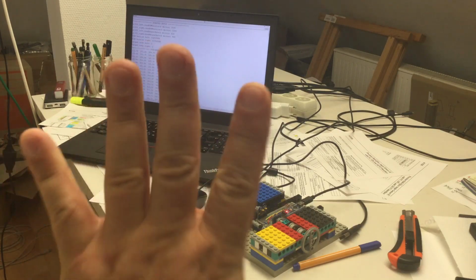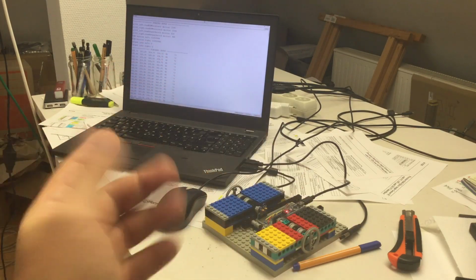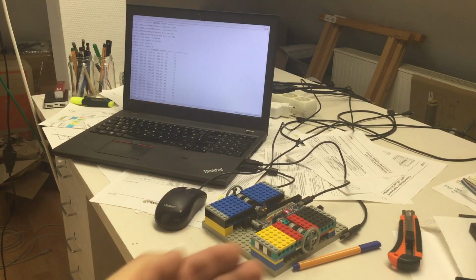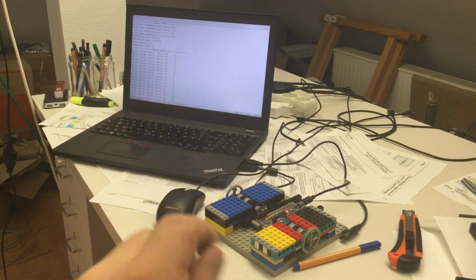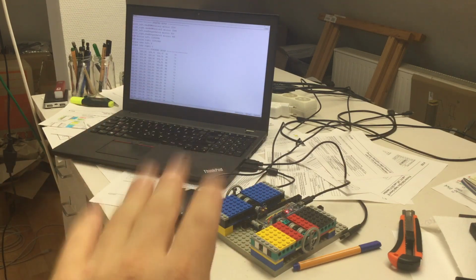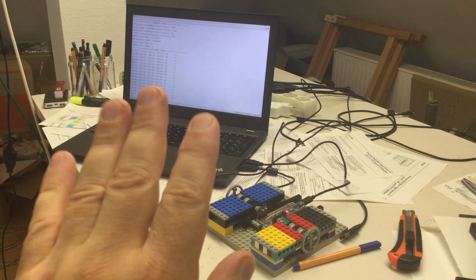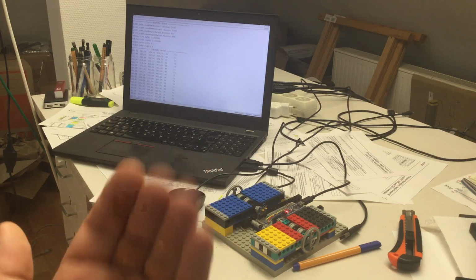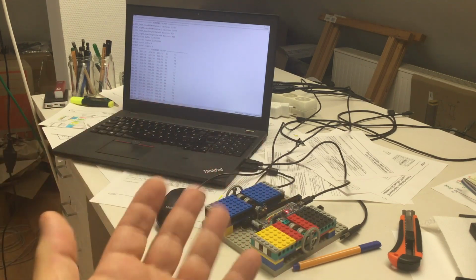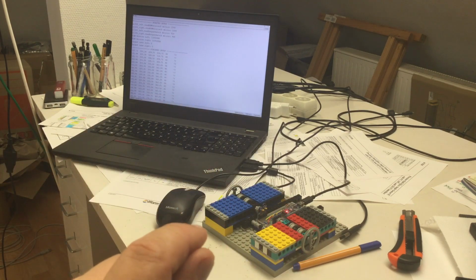Welcome back to the fourth part in the video series about the details of the Allegro A1335 precision Hall effect angle sensor. In the previous part, part 3, we left the primary 16-bit registers on their 8-bit addresses behind us and for the first time read some data from the extended 16-bit addresses, that is the extended 32-bit registers.